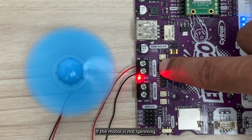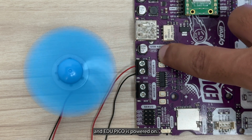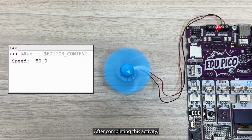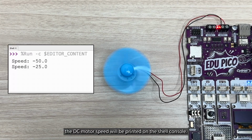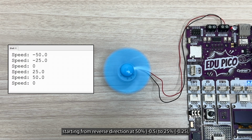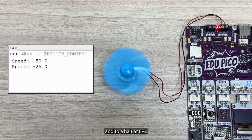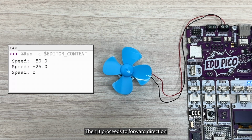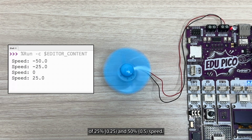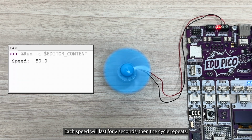If the motor is not spinning, make sure the wire connection at the terminal is secure and EDU PICO is powered on. After completing this activity, the DC motor speed will be printed on the shell console. It then continuously rotates at a different speed and direction, starting from reverse direction at 50%, to 25%, and to a halt at 0%. Then it proceeds to forward direction of 25% and 50% speed. Each speed will last for 2 seconds. Then the cycle repeats.